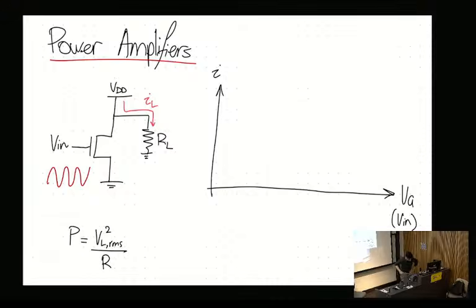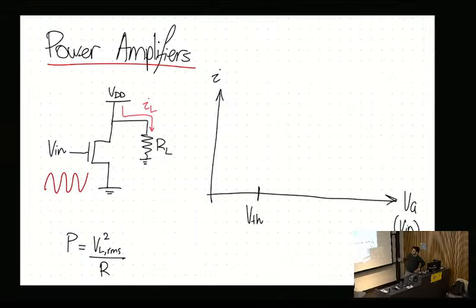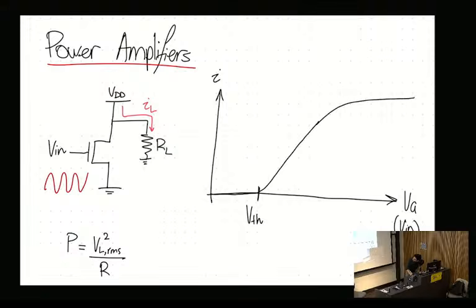Now, the MOSFET has a particular threshold voltage that is required at the gate before it actually turns on. Roughly, it's usually like 0.7 or something, it can differ. The specific value doesn't matter. All that matters is that there's some specific threshold. Up to this threshold point, the MOSFET won't turn on, but then it will. Once it turns on, it's sort of linear, and then it eventually saturates, right? So this is what we call the saturation point.